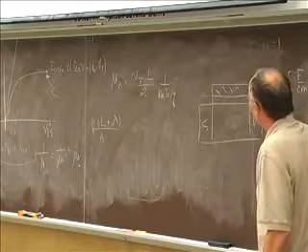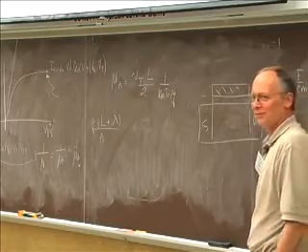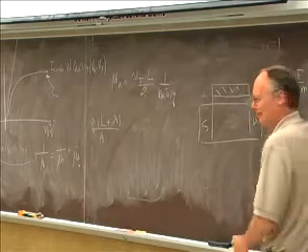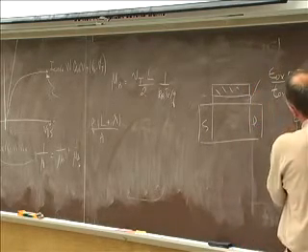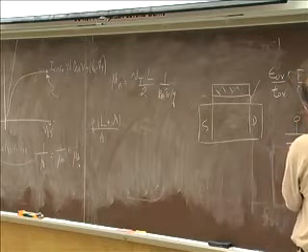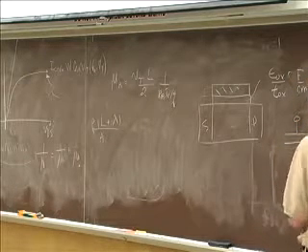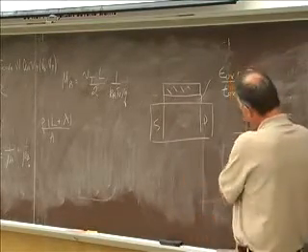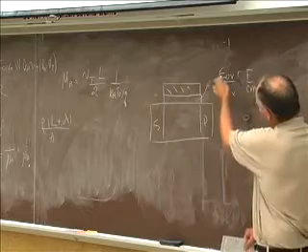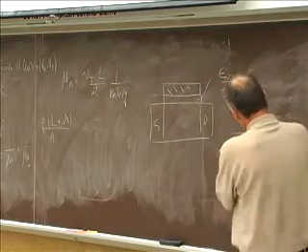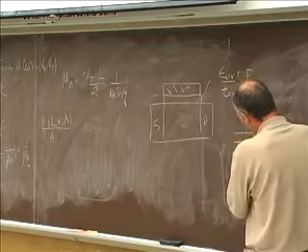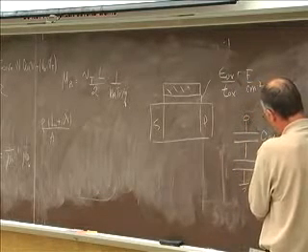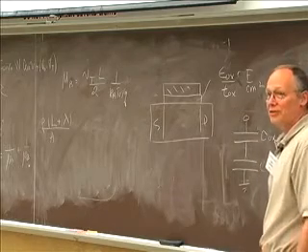But that's not quite true, because the semiconductor channel itself also has some capacitance. So the actual capacitance is this insulator capacitance, or if you've replaced SiO2 with something else, like Intel has, then it's some other insulator capacitance with a different dielectric constant. But it also has in series with it a semiconductor capacitance. Sometimes people call this the quantum capacitance. These two are in series.